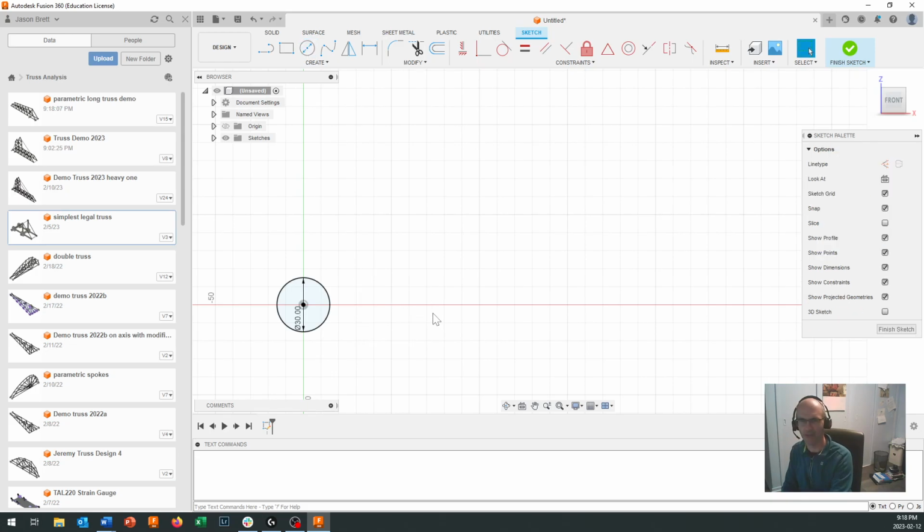Actually, before I do that, hold on. I'm going to create a line to connect these two because that is part of the process here. So I turn on construction line, okay? So on my sketch, there's going to be a construction line. I'm going to click on line, and from the center of that node, make sure you've got the center selected. I'm going to draw a line right in here, and I'm going to say right to there.